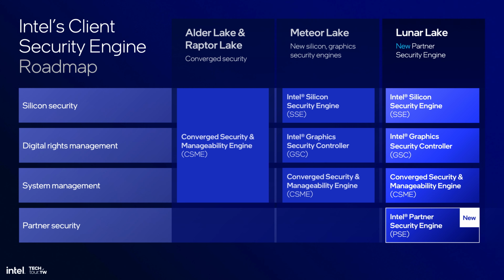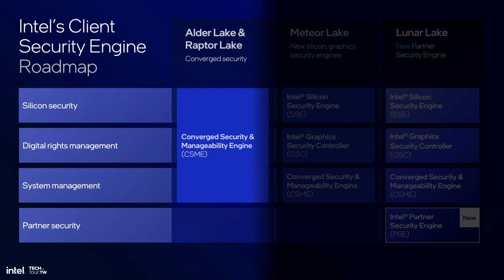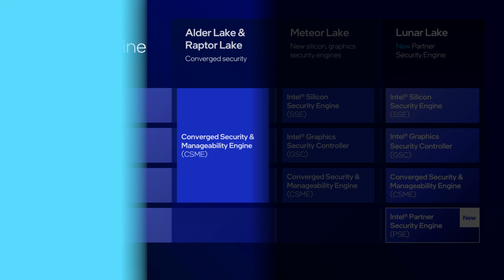Prior to Meteor Lake, all of our security services were converged into what is called the Converged Security and Manageability Engine. From a security perspective, when we design an SoC, the key things we look at are system management and flows, then security services that are required for the silicon, and then the digital rights management services that we kicked off a few years ago with Clarity and Widevine and other such usages. As I said, prior to Meteor Lake, all of this was part of the CSME engine. There is value in separating these usages into separate engines by themselves.